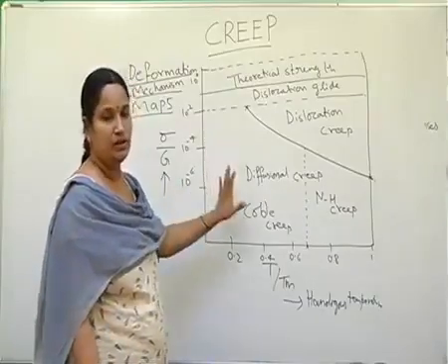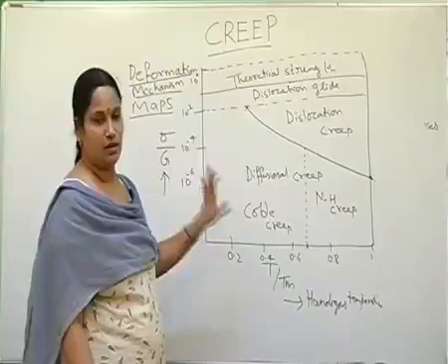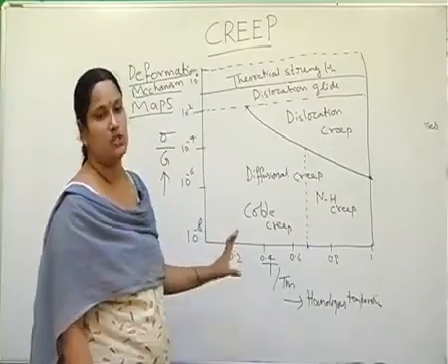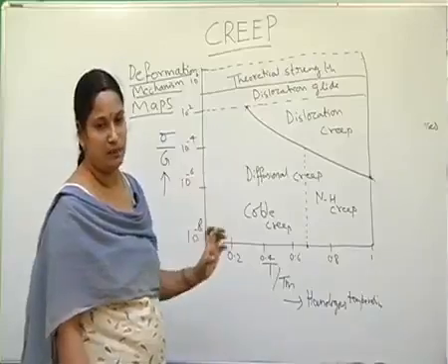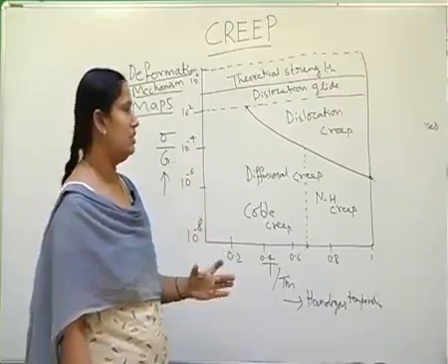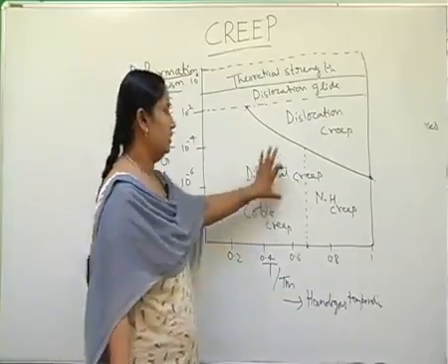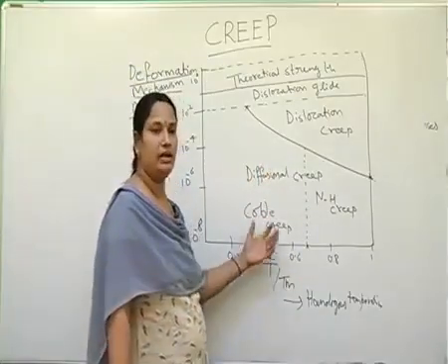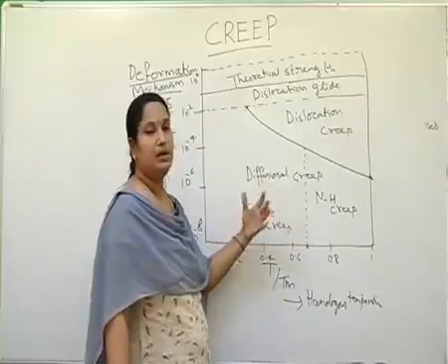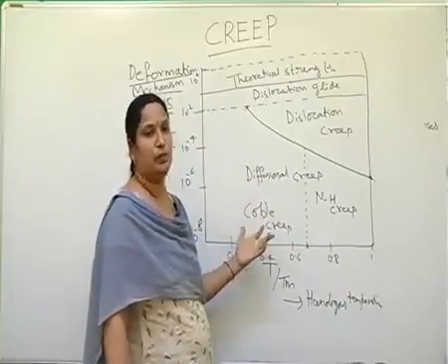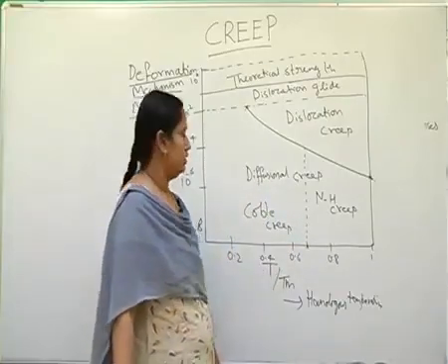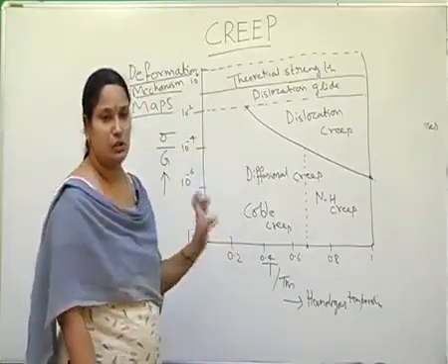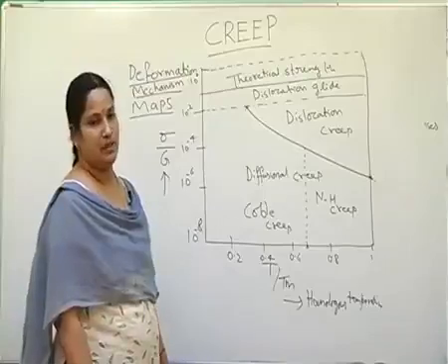By knowing the service temperature as well as the stress at which the component operates in a particular application, one can find out the dominant deformation mechanism. Accordingly, one can design the alloy to be creep resistant. These plots indicate the dominant creep deformation mechanism.